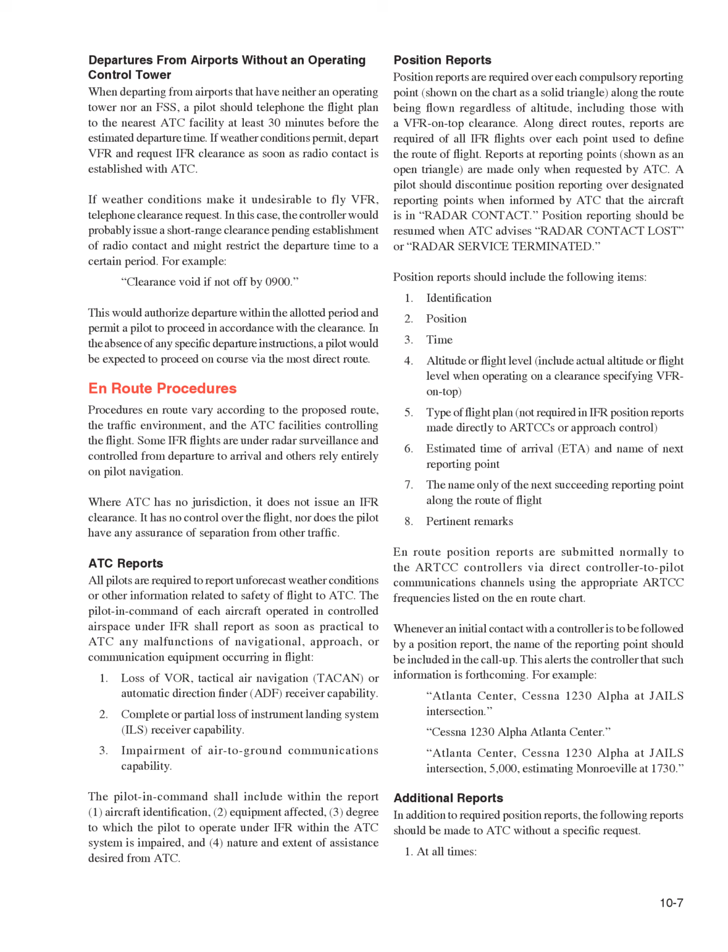The pilot in command shall include within the report: 1. Aircraft identification, 2. Equipment affected, 3. Degree to which the pilot's ability to operate under IFR within the ATC system is impaired, and 4. Nature and extent of assistance desired from ATC.